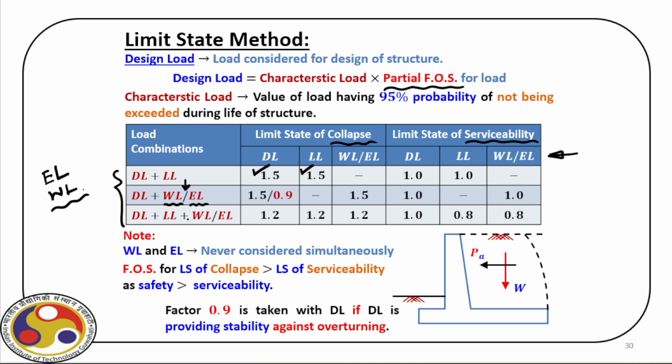Then we make a combination of loads. So we have dead load plus live load. Then if we have superimposed dead load, that also you have to consider. We'll go through all those different load categories and make combinations. But the point to be noted here is the combination of different loads, and we'll see in a minute that once we make these combinations, we have to identify which combination is offering the worst case, and then design the structure against those loads.